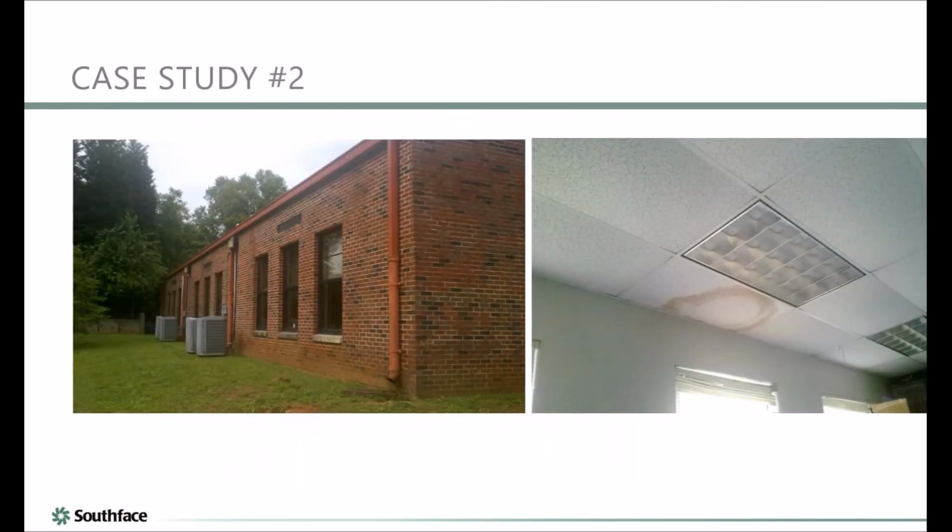This is another one that we also tested. This is an interesting one. We tested the older part of this school, and it had an attic space. It was a flat roof, but it basically had a flat ceiling with an attic space below the flat roof, and it was vented. And we removed all the old insulation. We did not vent it anymore. And all of a sudden that building got significantly tighter. We really improved our air sealing dramatically.